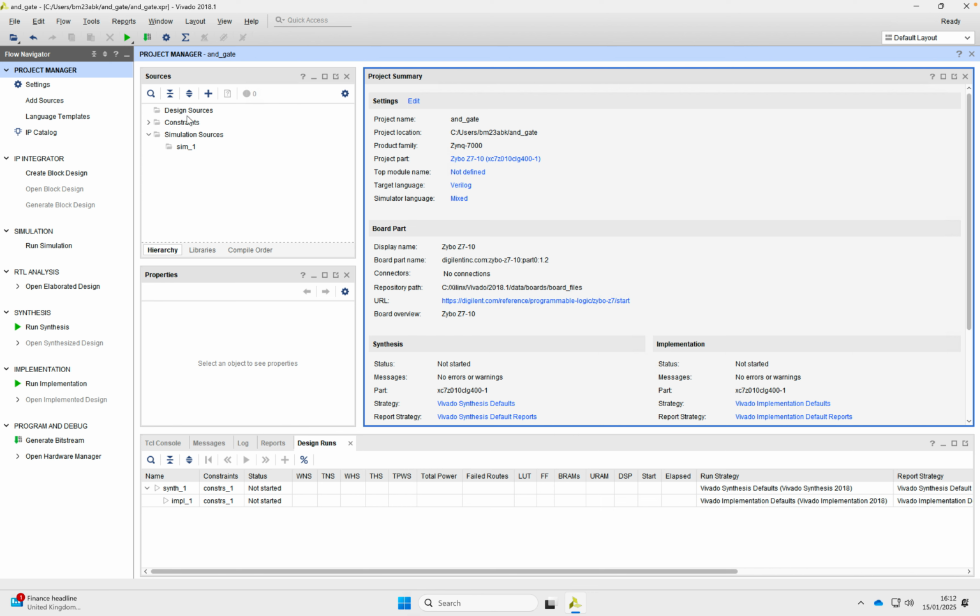After adding this, for us to implement it on a hardware, which is the Zybo Z710, which is part of the 7000 series, we need to run the simulation, run the synthesis, run implementation on the board, provided we did correct port mapping, which is specific to each project. We need to generate bitstream and then open a hardware manager. Then we can see the results on the hardware.